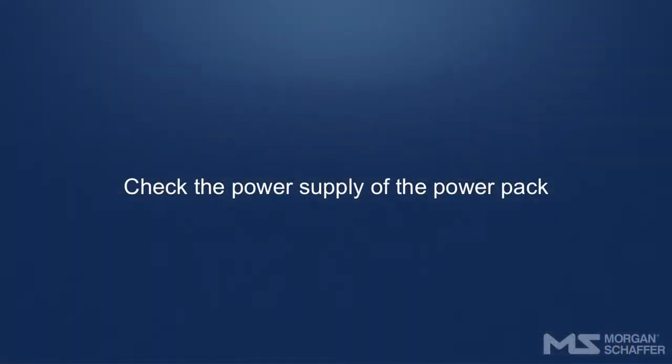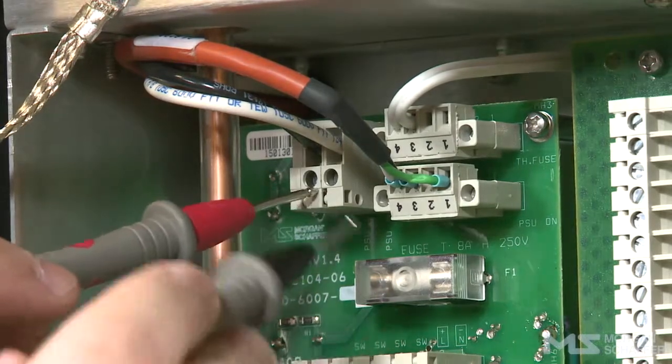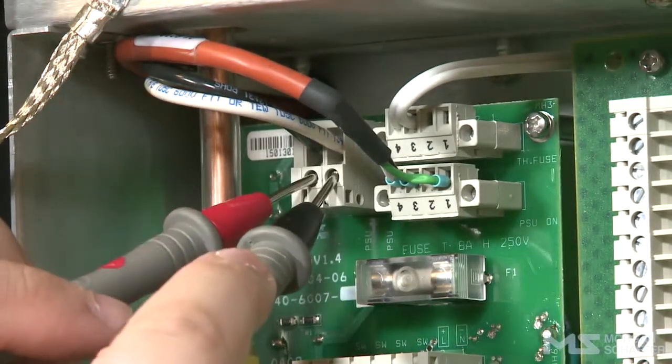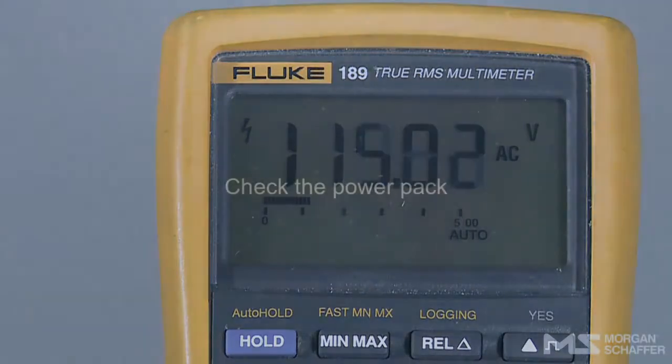Check the power supply of the power pack. Connect a multimeter between pins 1 and 2 of the TB2 connector. The voltage must be between 100 and 240 volts alternating current, or 100 and 220 volts direct current. If this is not the case, check the condition of the fuses.